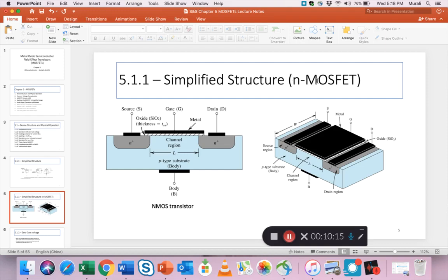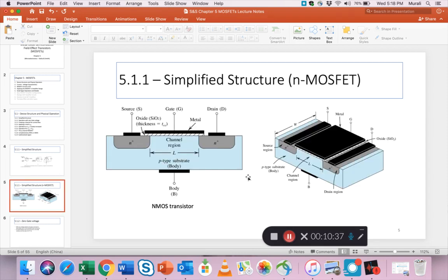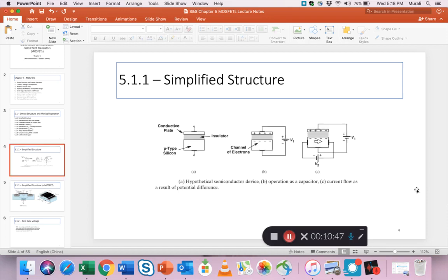This is an N-type MOSFET. So as you can imagine, there's going to be a P-type MOSFET also. Similar to your NPN transistor and PNP transistor, we have these NMOS transistors and PMOS transistors. Okay, NMOS FETs and PMOS FETs is the right way to say it. Okay, so first of all, since we got this terminal out, the gate terminal, we have to start thinking about applying voltages, right? Because remember, in slide 4 we said you need two types of voltages to have the FET actually operate and give us some benefit.